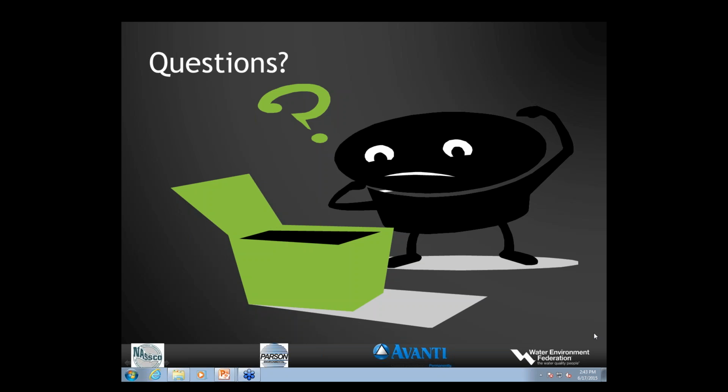You can step up to a NACE type training, which is more intense. It's a longer training period. It gets into actually doing some of the tests and the performance of the tests. By the way, the NACE inspectors, the independent third-party inspectors, are available. You can pretty much go up on a website and look in your area for who is a NACE certified inspector. And putting a third-party inspector on a job site is, quite frankly, the next step up above having a typical inspector training.